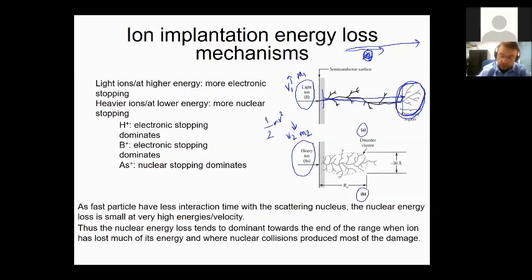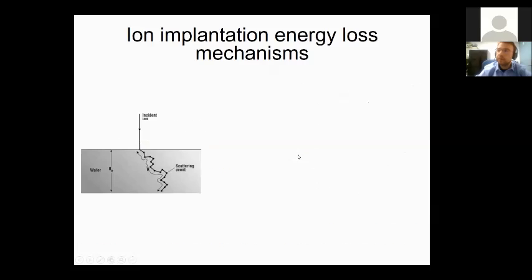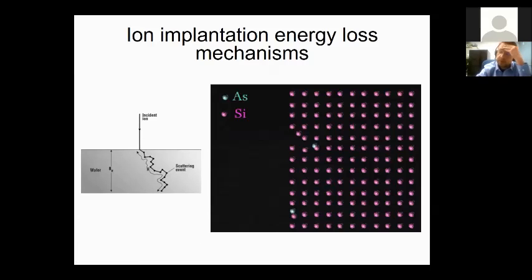As for the arsenic, at the starting point it doesn't have that kind of velocity, and it will start interrupting the crystal structure already initially. I hope the time will permit, I'll show you in SRIM, the simulation tool that we use. But arsenic is now penetrating in, as you can see, and it's dislocating the silicon atom. We have seen these defects. We didn't see them in ion implantation, but we have seen these defects getting formed. These were the interstitial silicon atoms that were created, and if the arsenic was stopped, that would be a foreign atom point defect structure